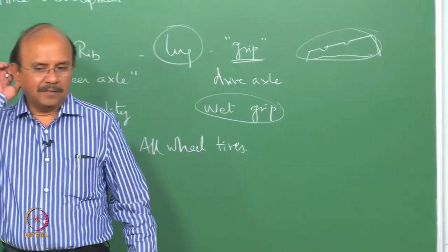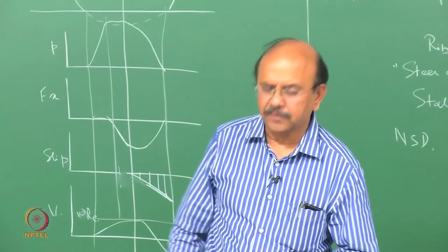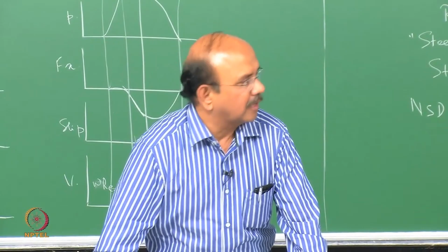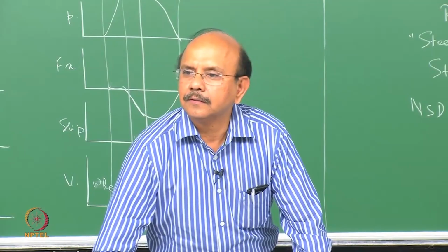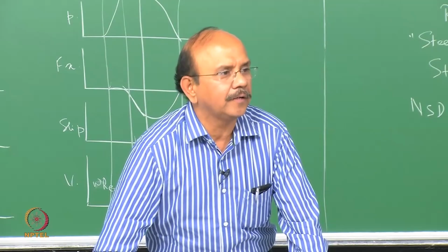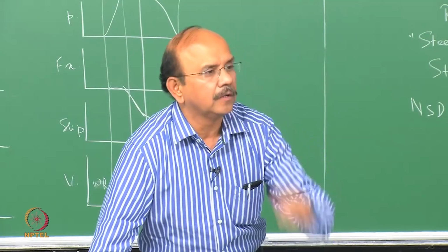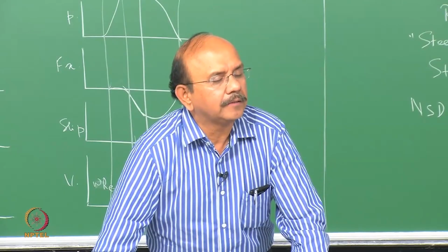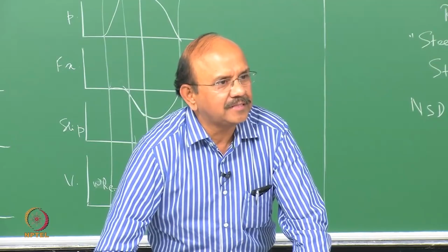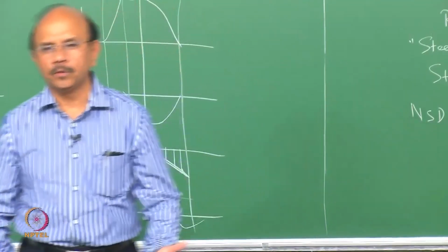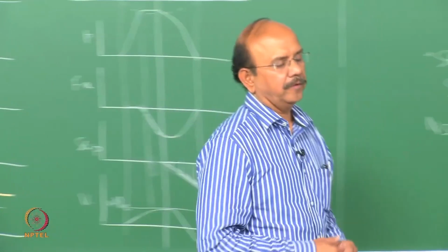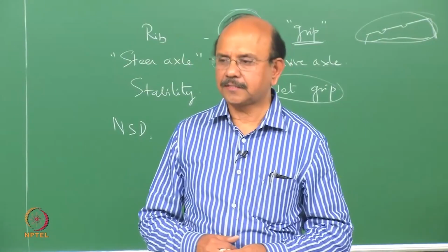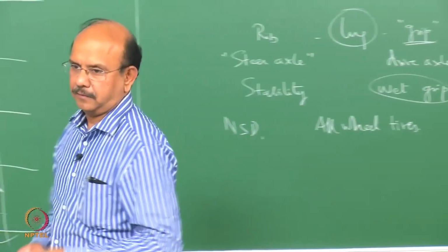Due to certain reasons which we won't be able to discuss now, the bias tires' contact pressure distribution is very different. I said that we're not going to go into the details of contact pressure distribution in a bias tire, but because of that, these tires are not very prone to the vehicle geometry, and hence people prefer to put the bias tires in the front.